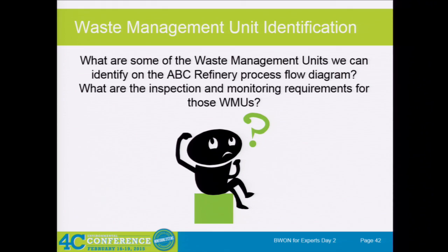But for MSS, for those in Texas, and pretty soon many other states will be falling in, you actually have to control the vent off of a vacuum truck if you are using it for maintenance activities and it's greater than 0.5 psi vapor pressure, with carbon cans or something. That's only in Texas. At this point, it's only in Texas, I believe. I don't think the MSS regulations have spread, because each state is creating their own based on the SIP.